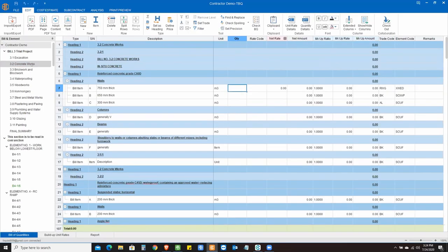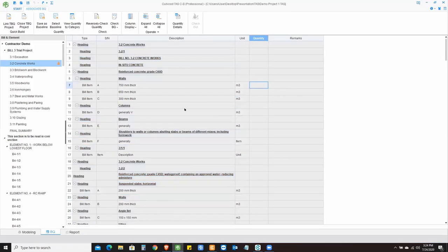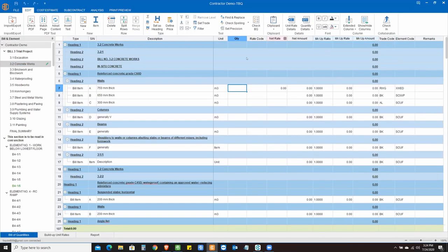Now you might be wondering about the edit functions in both the softwares, because if somebody is working in one software, and another person is working on the same bill item or same element, then it contradicts. So how do we deal with that? You have got this checkout option here. If you click on that, then basically it takes away the edit function from the TAS software. So the person who is using TAS won't be able to edit that particular element anymore. Similar thing goes back the other way: if you check out from there, then it locks here. Okay, so I'm just going to say check out just to edit there.